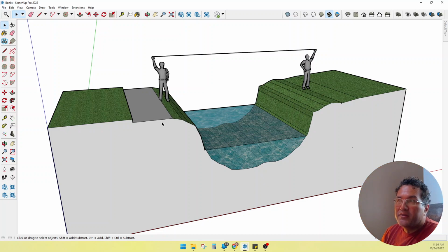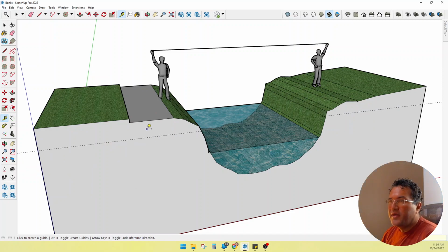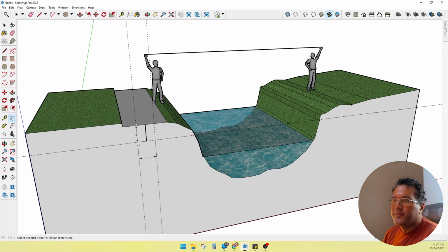Typically, our ideal bearing area that we want to use as an abutment is about 2 foot by 2 foot. 2 foot in this direction, 2 foot down, 24 inches. And then, if you're going to put your abutment, let's say here at the center line, you'd want it 12 inches in this direction and 12 inches in that direction, right about there. So that way now we're talking about 2 foot by about 2 foot. Okay, and then the area in the other direction. So now we have the depth and the height.